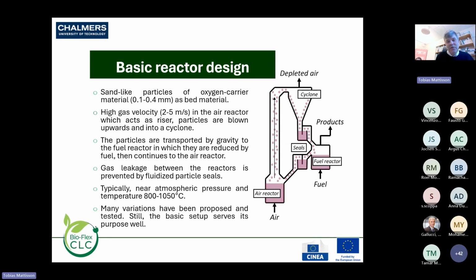You have a high velocity air reactor, which is coupled to a cyclone, and then on the return side, the fuel reactor. Fluidized bed is a technology very well known for transferring particles like sand in conventional fluidized bed combustion.